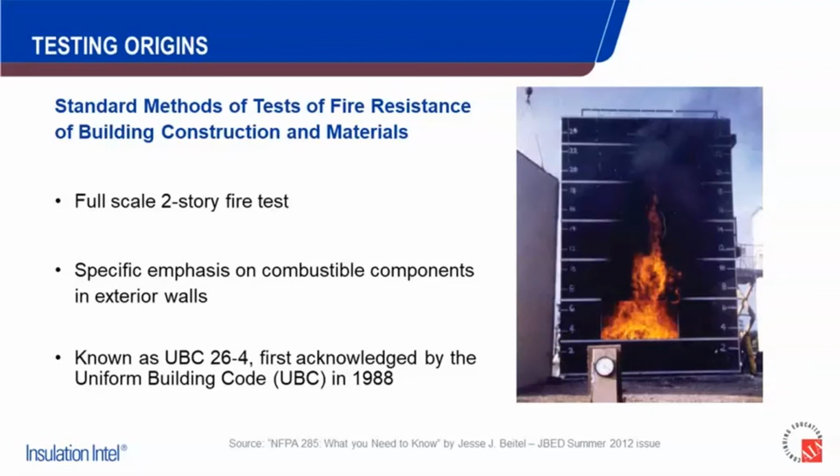And what you see here, again, full-scale test, meaning you're mocking up literally a full-scale model of a building. So the full wall system, the structure, everything at a minimum of 2 stories, and we're essentially burning that to the ground, and then taking a bunch of measurements along the way to understand how the flame is spreading, how fast it's spreading, how hot the structure is getting, etc.